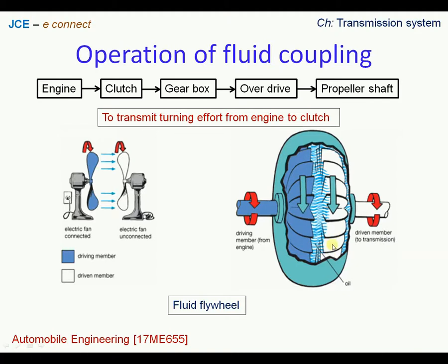For an efficient fluid coupling, there should not be any lag in power transmission. When the right side impeller is stationary, the efficiency of the fluid coupling is almost zero. When the rotation speed of the driving impeller matches the impeller on the right side, the fluid coupling is around 99% efficient.